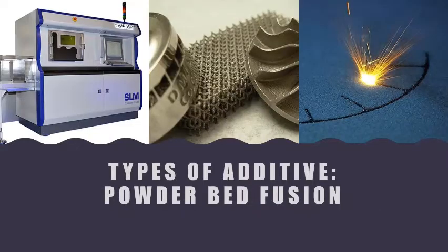Powder bed fusion is a process like vat polymerization. It consists of a bed full of powder that is selectively melted by a focused laser beam. After each layer, more powder is deposited on top. The process repeats layer upon layer until the part is complete. Common materials are powdered metals and polymers.